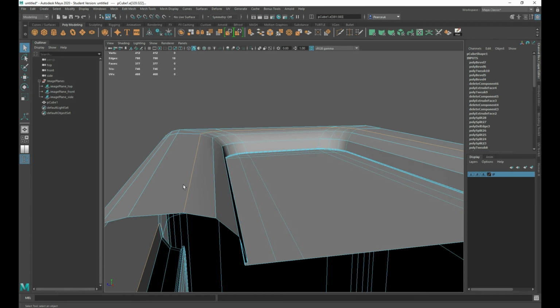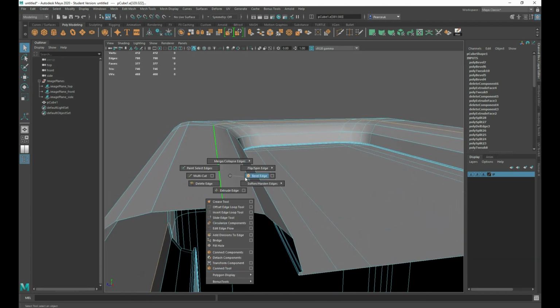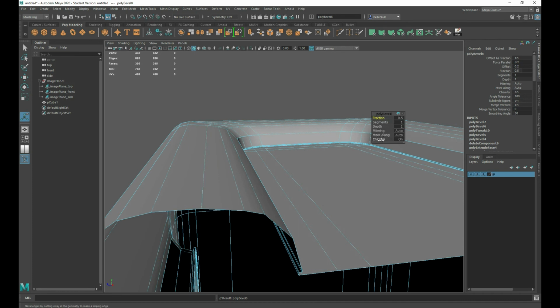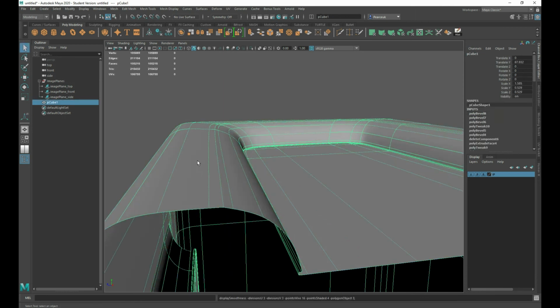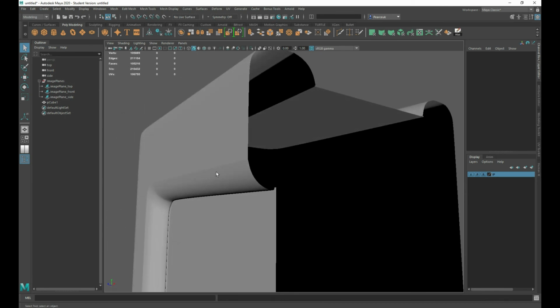and I'm going to bevel it, take the chamfer off, reduce the fraction, so maybe 0.5, nope, 0.1, hit Q on the keyboard, and then when we hit 3, it will just, or it should, hold that edge a little bit better, although it's not that much of a sharp edge.